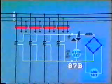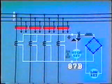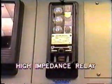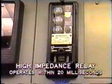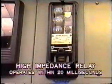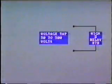A range of pickup current settings are available from 2 amps and up. This is a plunger type relay which will trip within about 8 milliseconds, that is less than 1 cycle. This is extremely high-speed operation. The lighter bus faults will be cleared by the high impedance relay, and this operates within 20 milliseconds, that's about 1.5 cycles. This is also extremely fast operation. The setting of the high impedance relay is achieved by selecting the correct voltage tap, usually between 50 volts up to 500 volts.